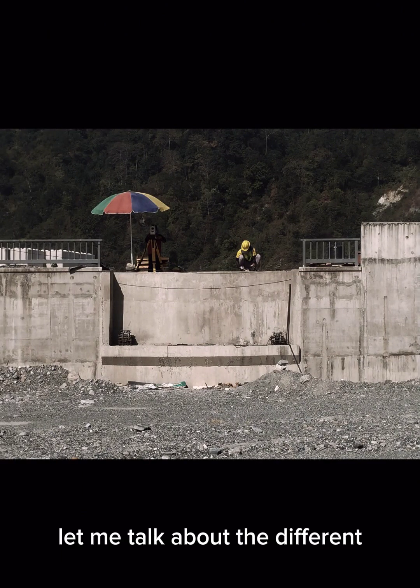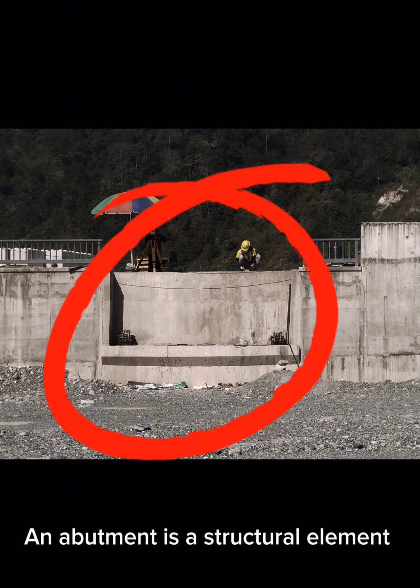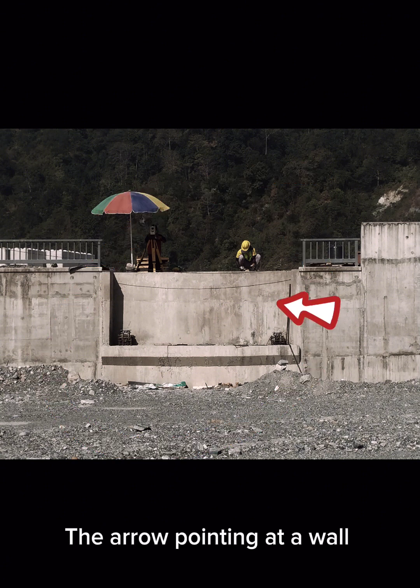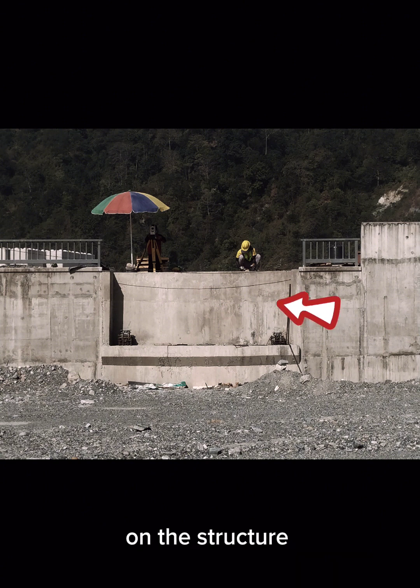Let me talk about the different components of abutment. This structure here is called an abutment. An abutment is a structural element that transfers loads from a bridge to the ground or supporting structure. The arrow pointing at a wall is called a dirt wall and it functions to resist the horizontal forces acting on the structure. The horizontal force here includes the soil pressure exerting from the back of the dirt wall.